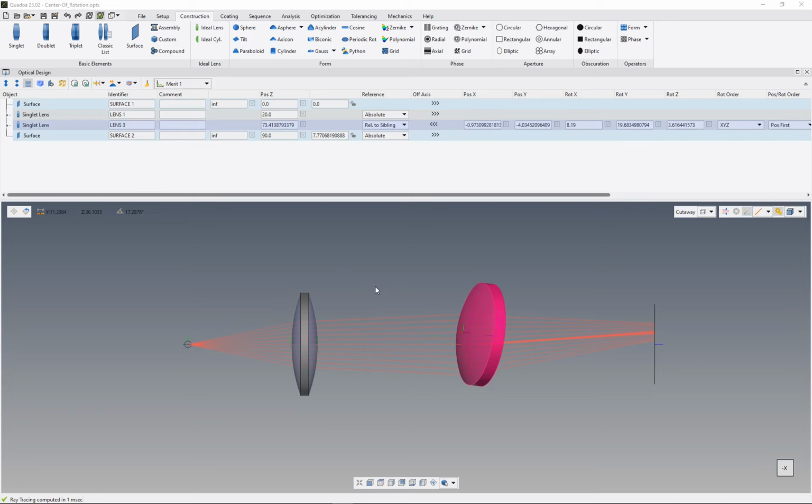To set up the correct position dependencies is of course very important for accurate tolerancing results. So after you've set up your optical system in the for you most convenient intuitive way, you can just convert afterwards all the dependencies without affecting and changing the positions of the elements. And as I mentioned, the correct definition of the dependencies of the lenses is of course of very high importance